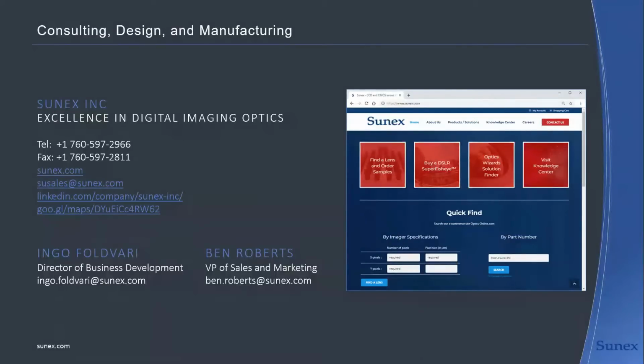Online on our resources page, there is a white paper about CRA mismatch that I recommend that you read if you're interested in CRA effects. But in every use case and with every sensor and with every lens, the result is a little bit different. Some lenses and sensors have extremely tolerant CRAs, and it will work, you know, even if there's tens of degrees of mismatch. Other sensors and applications and lenses are more critical of CRA mismatch. So unfortunately, not a super straightforward answer, but hopefully that helps provide some guidance.